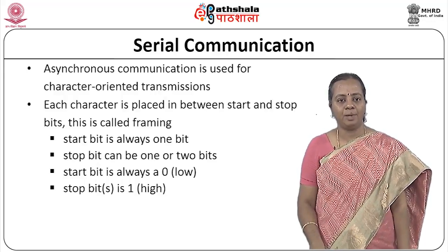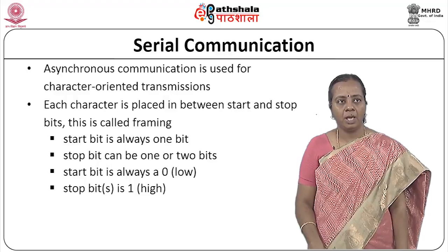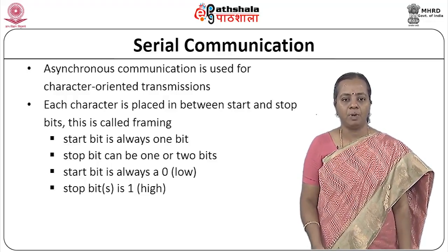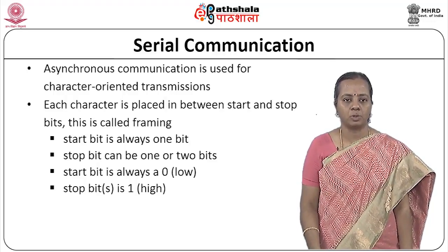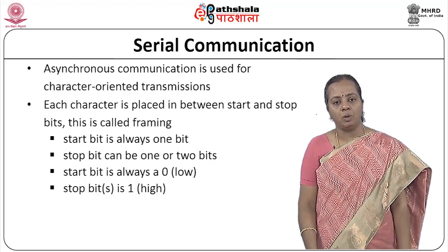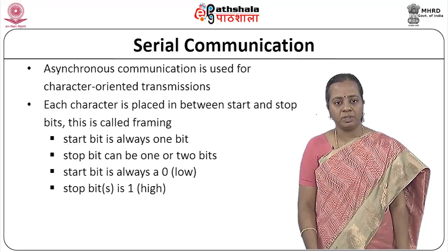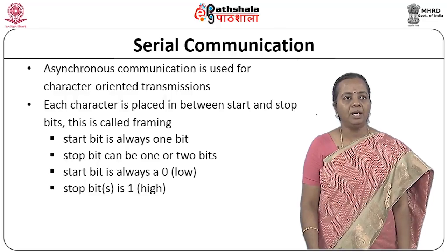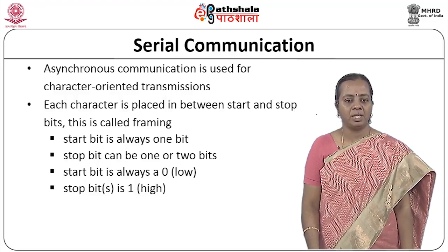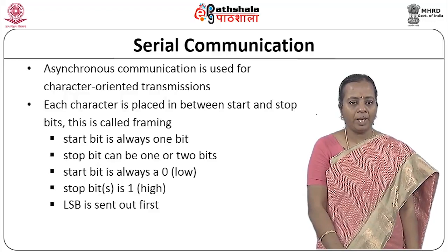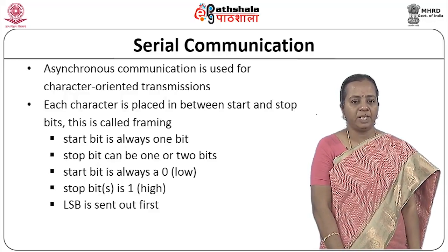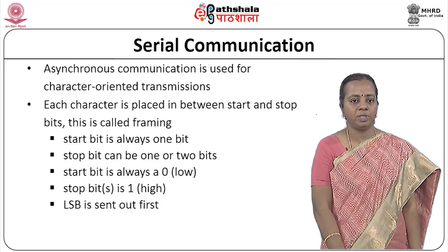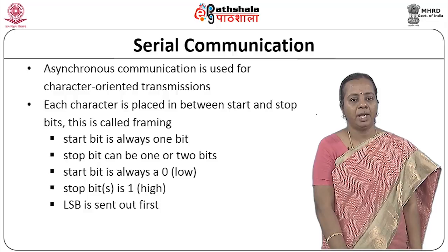Always only one start bit will be used, and the stop bit may be 1 bit, or some systems have 2 bits also. But the start bit is always 0. With respect to the 8051 UART, the start bit is 0, that means a low level signal, and the stop bit is a high signal, which is 1. In the data sending, the LSB will be sent first, and the MSB will go last in those 8 bits.